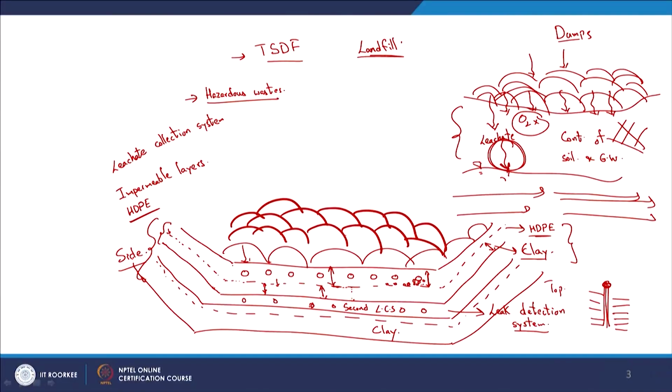And how is this slope going to be looked at in the slides? Typically, all these layers are supposed to be taken up here, and there is a trench here and then here, and this trench is filled with particular material. Why is that required? If wind blows, you don't want this wind entrapping air underneath these pockets of impermeable layers, right. So to prevent slippage, you don't want this layer to slip, and also to prevent uplift by wind, you want to have a continuous trench around the perimeter of your landfill, right. Again, we will come across this in greater detail.